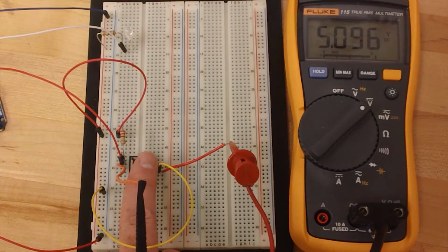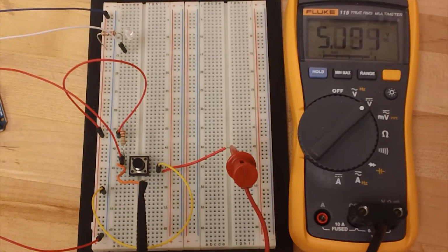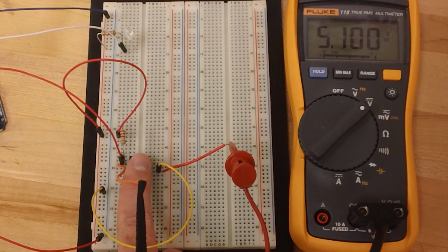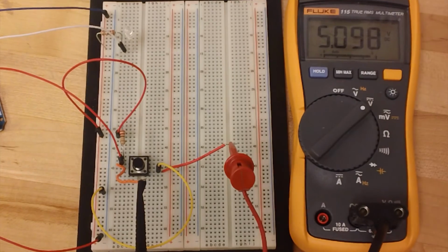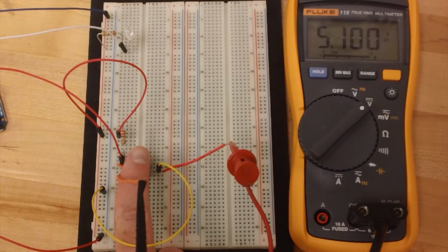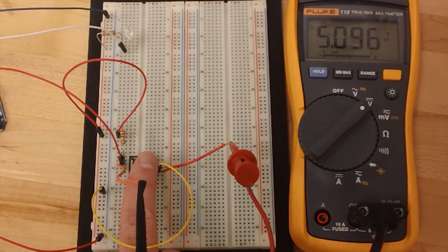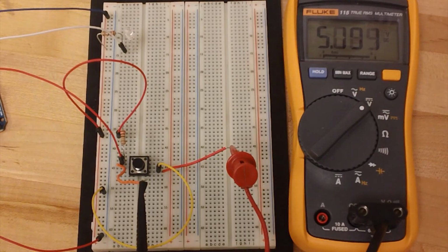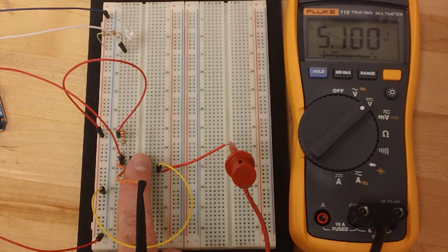The first thing you should check is your LED. Make sure that it operates if it is supplied power directly. If it does not light up, change out your LED. Next, you should check the voltage of the button pin. If there is no voltage, you may have your button turned the wrong way. The third thing you should check is your code. Make sure the pin numbers correspond with how you set up your circuit. If the LED is still not lighting up, check to make sure you have the positive and negative leads of the LED in the right place. Finally, check the resistances of the resistors in the circuit. If the resistances are too high, not enough voltage may be making it through the circuit.